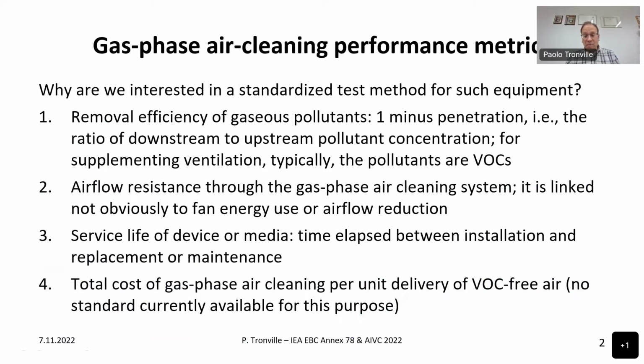The second parameter that is used for assessing the performance of gas cleaning devices is the airflow resistance. This is in some way associated with the cost of operation. Not obviously, because many times high airflow resistance means lower airflow delivered into the space. So the fan energy use can be correlated to the pressure drop of the device only if there is a device that compensates for the increase of pressure drop, like a variable frequency drive that is used to maintain the flow constant.